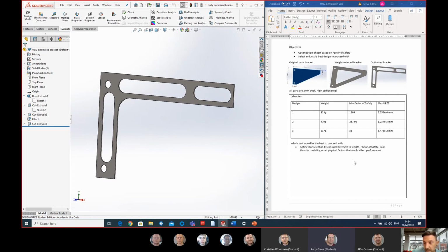Okay. What about part cost and manufacturability? Is there any difference between these 3? Wouldn't that be cheaper? That'd be more expensive. Yeah. It would be less material, but probably more expensive to make because you've got to cut the holes out. You've got to cut these extra bits. You've got stamping and machining on there, but then you could look at, can you get more pieces out of a sheet because you've got that cutaway section between the angles? Yeah, indeed. So the material usage as well.